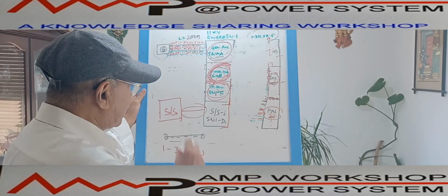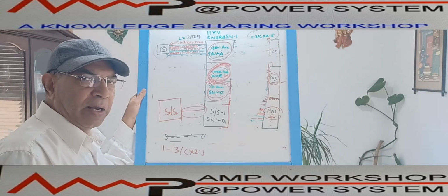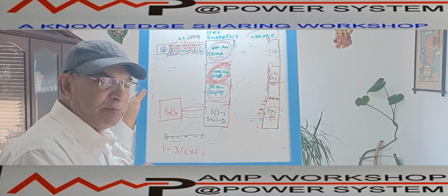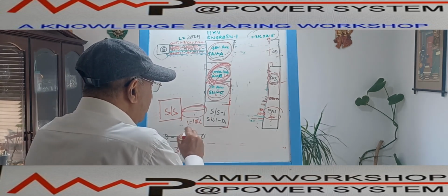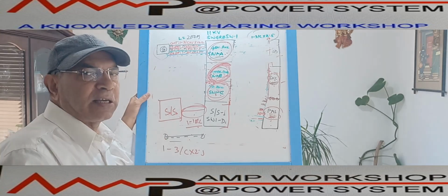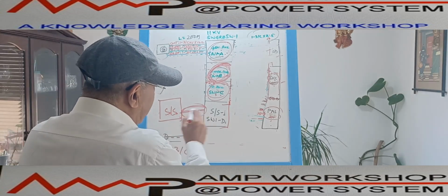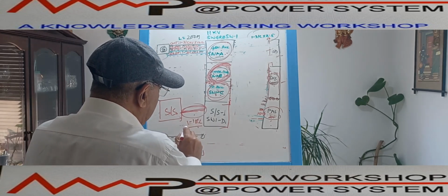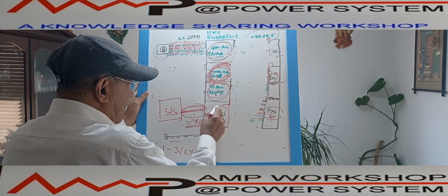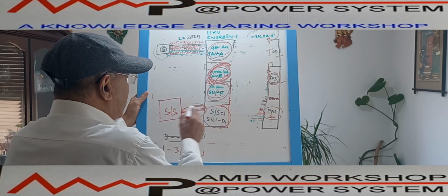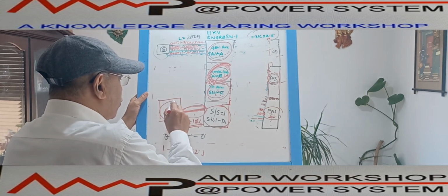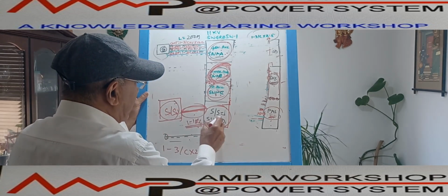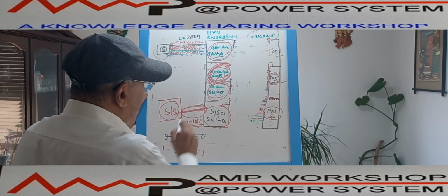This cable is a subsea cable, and in the previous video we considered this 18-core control cable as built into the subsea cable. So that cable is already included, and through this single 18-core cable, whatever status we monitor from here to here, that signal goes, and if we want to control this circuit breaker remotely, that command also comes through this.